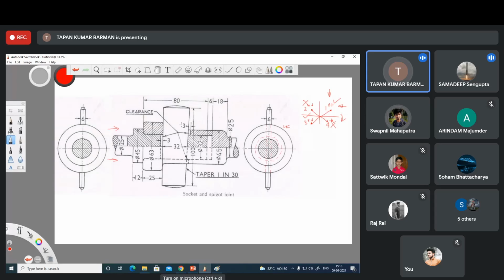No, you will get it. The orientation of the hatch line will be different, and hatch line is one thing. Another thing is we will get a dotted line in this view. I am changing here from this point to this point, and this should be a thick line, because when you are taking the projection from this direction, you can see up to this. These components should be visible up to this, right?